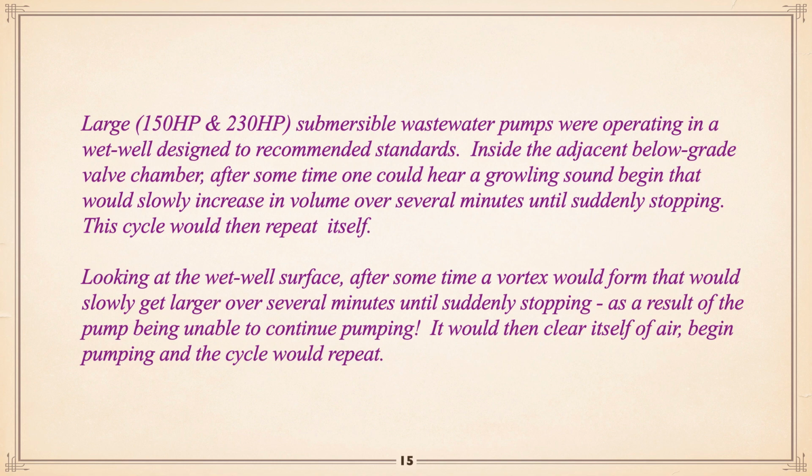If you looked at the wet well surface, after a time, a vortex would form that would slowly get larger and larger and larger over several minutes. Air is now going into the pump, causing the growling, until suddenly it would stop because the pump had so much air it choked on it and was unable to pump. Then it would clear itself of air, start pumping again, and the cycle would repeat itself.